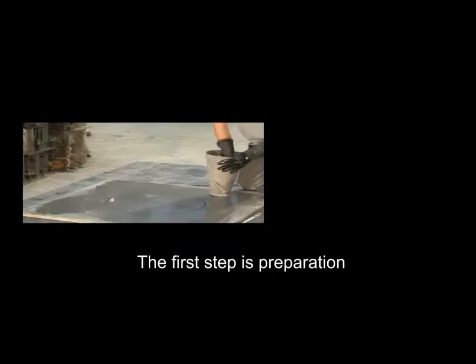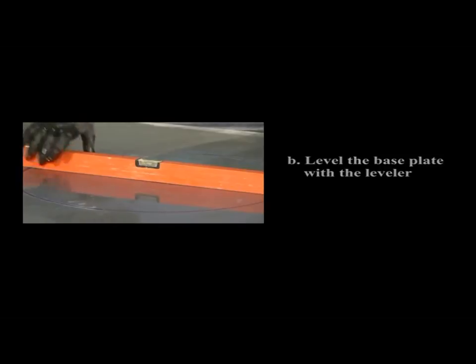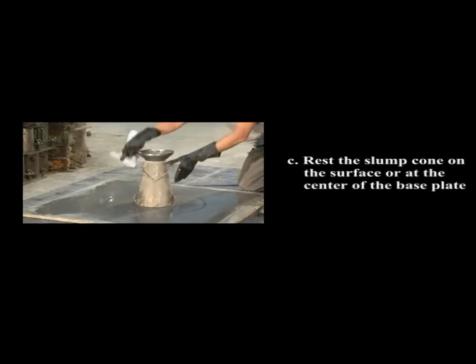The first step is preparation. A. Dampen the slump cone with moist cloth. B. Level the base plate with the leveler. C. Rest the slump cone on the surface or at the center of the base plate.